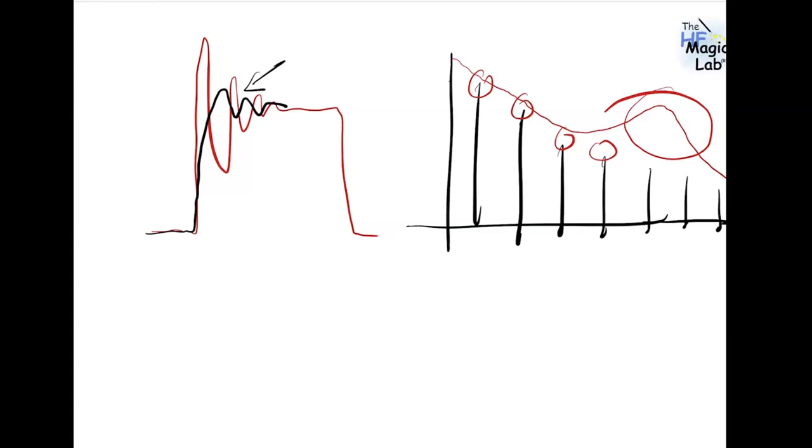Next up, can you emphasize the quasi-peak and average measurements, the difference between the two, and any best practice considerations we should follow? Well, you have three basic detectors: the peak detector, the quasi-peak detector, and the average detector. The peak detector is looking for the peak of the signal, the peak of the EMI you are injecting. The average detector is identifying the average of this signal. And the quasi-peak is some kind of detection of how repetitive the peak is.